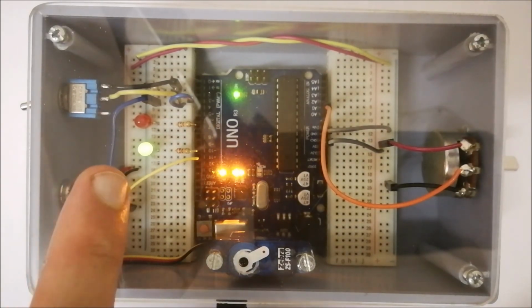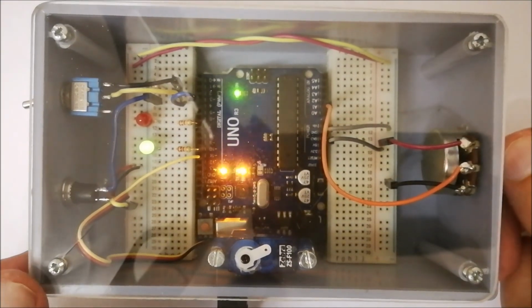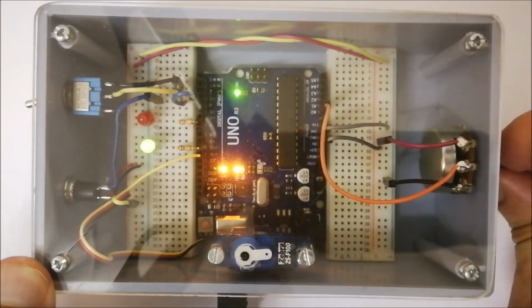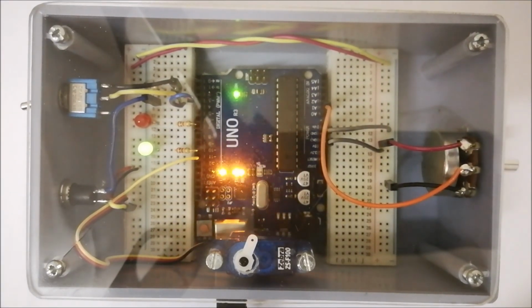So that would be the command you would have for the green light. Depending on the PWM output that we're giving, again ranging from 0 to 256, and again correlating with the voltage from 0 to 5 volts, depending on the voltage that we are able to produce coming out of the PWM, we're able to then control the speed of the motor. Keep in mind that motors are not linear.